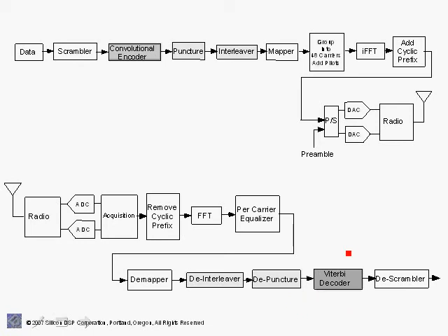In 802.11a, the convolutional encoder uses what you call a constraint length equal to 7, and compared to unencoded, using no coding at all, for example, if you were using BPSK, binary phase shift keying, a convolutional encoder with a Viterbi decoder with a constraint length equal to 7 actually achieves about 5.5 dB of gain. And what this translates to is that the receiver sensitivity has increased considerably.